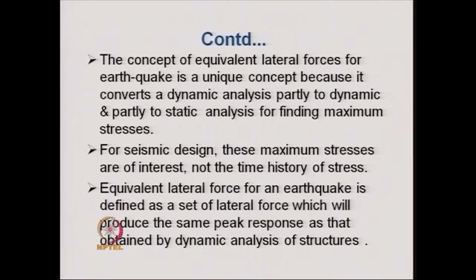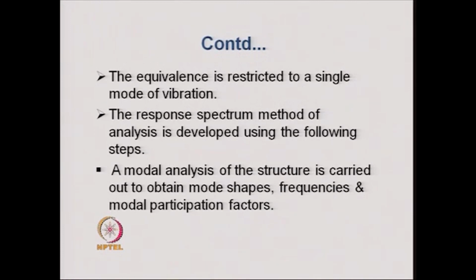So, if it is assumed that the structure is vibrating only in one mode, then this equivalent lateral force can straightaway provide us the maximum response the structure would undergo in that particular mode of vibration. Obviously, the equivalence is restricted to a single mode of vibration.